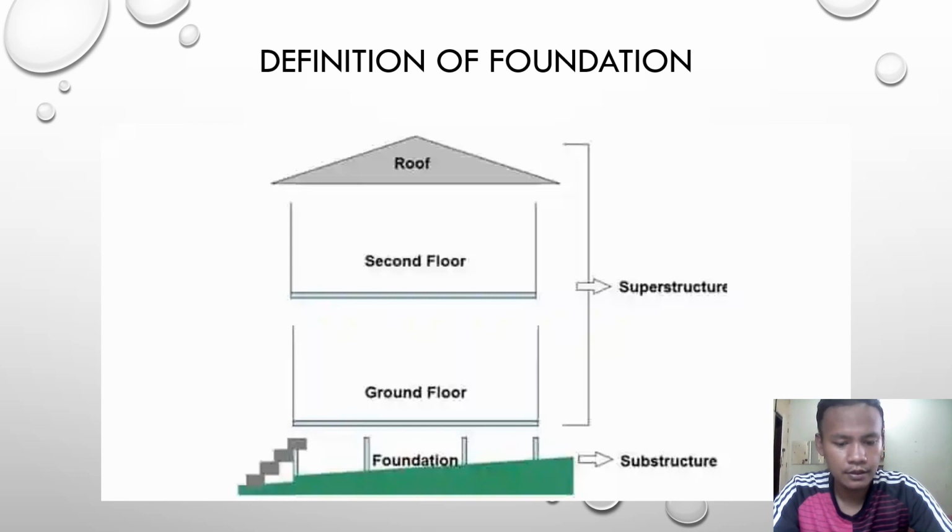Here are some types of foundation that are commonly used for building structures, namely strip foundation, raft foundation, and pile foundation. Strip foundation, or strip footing, offers support for linear construction such as a wall or closely spaced columns.